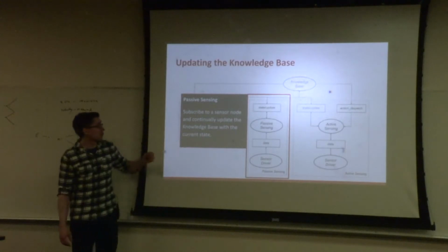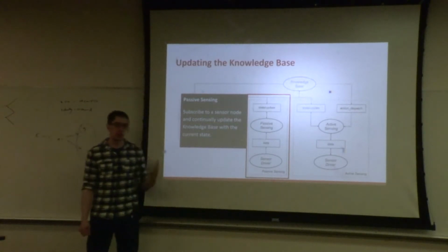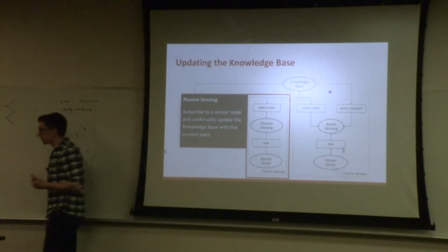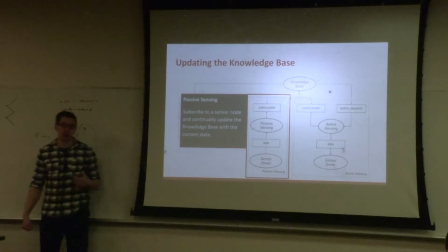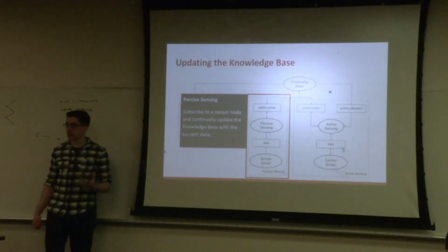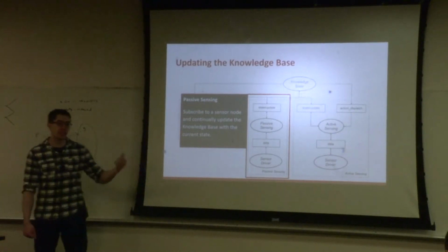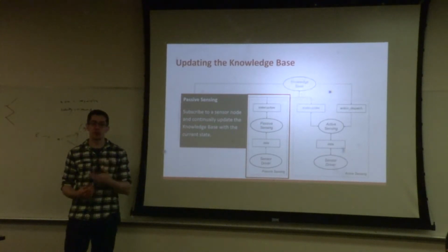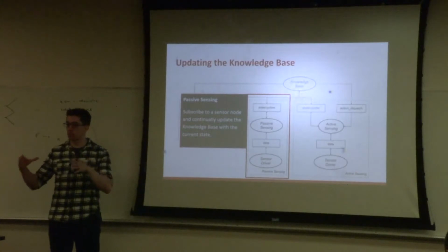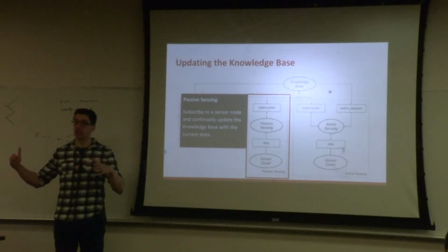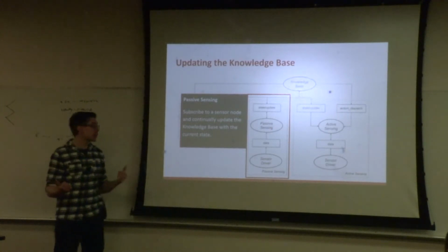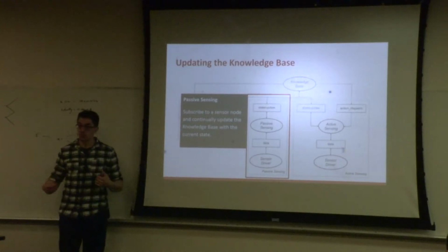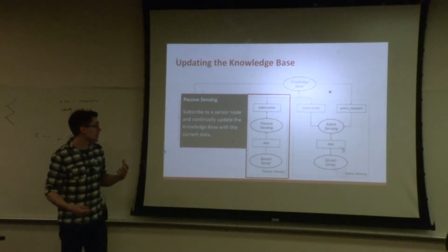And in contrast to that, passive sensing is something that's probably not so computationally expensive, and you can just do it all the time. So the localization by AMCL is passive sensing. It's reading that scan data, trying to match it to the map, and publishing this cloud of points with orientations, those green arrows on the visualization. And it's doing this all the time. It's publishing with quite a high rate.